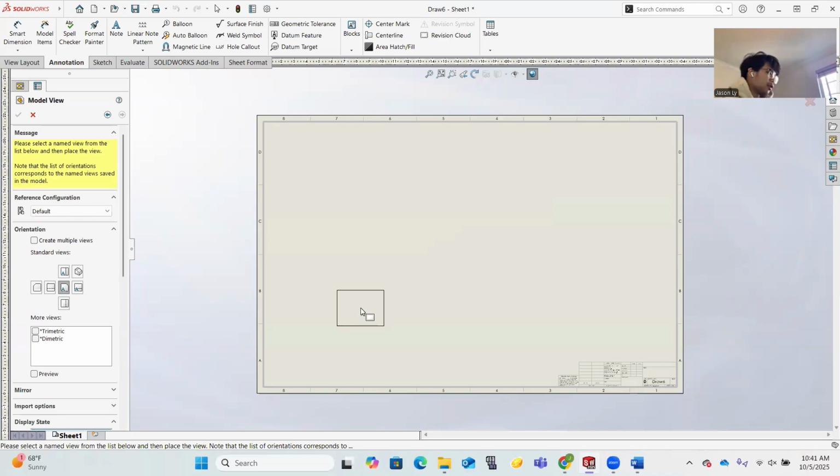So again, for the three things I need the standard view, right? So standard view, it's going to be your front, top, and right faces. So right here, this is where the faces you see, right? So typically it's going to be your top, front, and right. So it starts with your top, then right, I mean front, right, left, back, top, bottom, right? And like I said in class, your top view can only come out of your front. So automatically, since these are three in a row, we know this is top, front, and bottom, right?